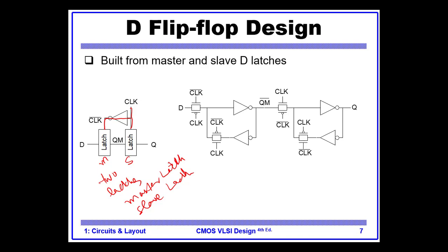Because of how the clock signal is connected to the master and slave, with a NOT gate, there is no point in time at which both latches are transparent.